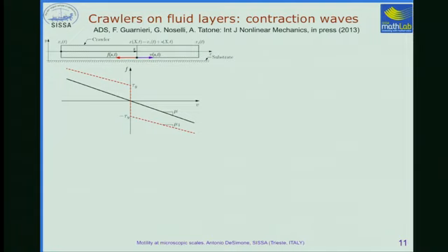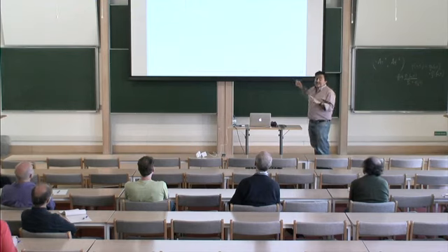And another one is represented by this graph, in which the force can be nonlinear, and in particular there's an interval of forces that can be exerted at zero velocity. That is the yield value of the force, the force you have to exceed in order to move. Like in friction, like in Bingham fluids.